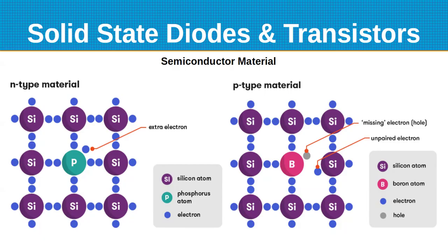And they learned that you can essentially enhance this characteristic by what they call doping. So if you take a piece of silicon, and they grow silicon as large crystals, and they machine very thin slices, and you'll see these big round white things, which are silicon wafers that they use in processing. They use different processes, but in these doping processes, they will add another material. So in this case, over on the left, we will dope it with phosphorus atoms. And those phosphorus atoms work their way into this silicon crystal matrix.